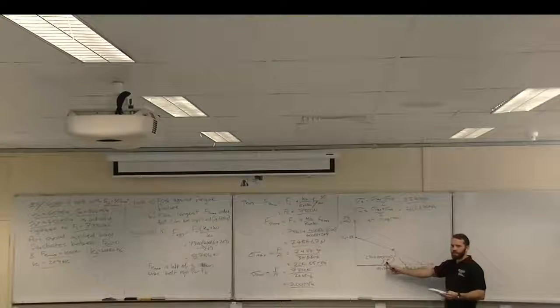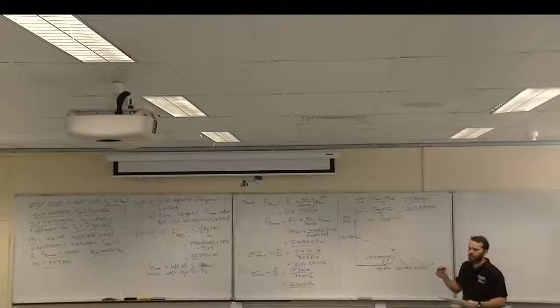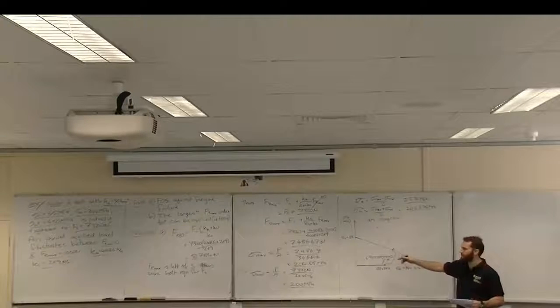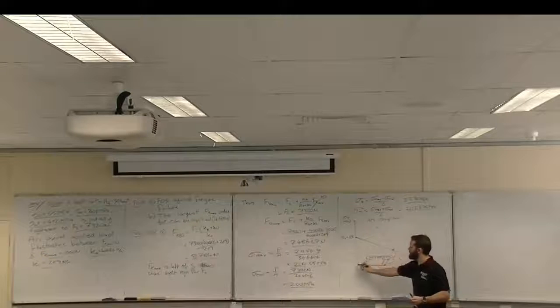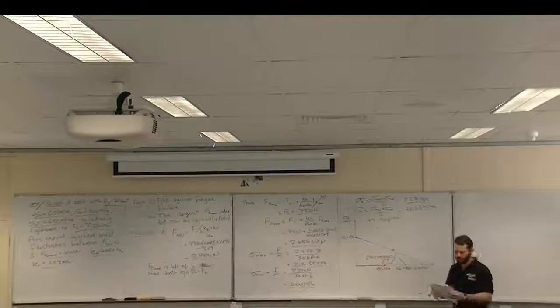We'll work out an equation to this line. I'll just do the two equations to the lines and solve it that way. You can do it however you want, you can throw it into whatever. Remember that the Goodman line doesn't have that one on n anymore because we've already dealt with n elsewhere, or we're calculating n. The one on n in the Goodman equation assumes that the intercept is here, and so we don't use that for bolts.